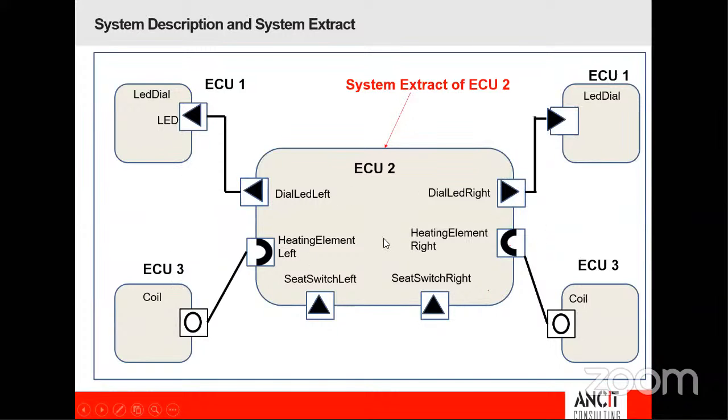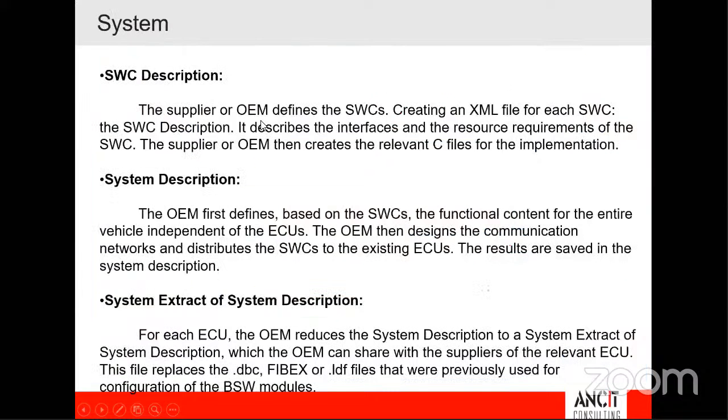And like we mentioned, it has 5 application software components, and we have created these application software components in ARXML, on Artop, and generated an XML file. So that's step 1, what we call creating an application software component description. Right? It's an XML file.